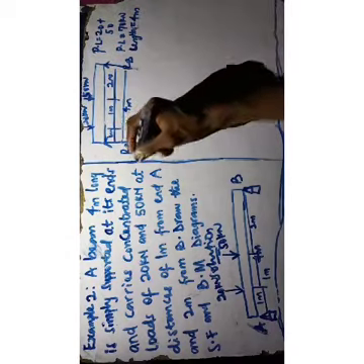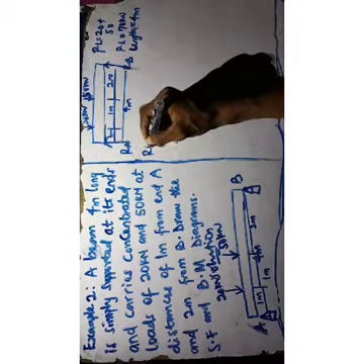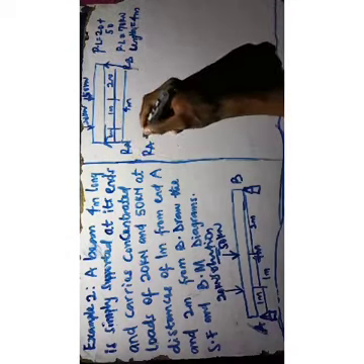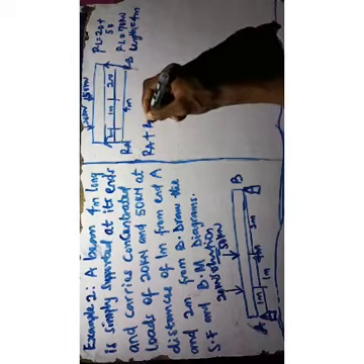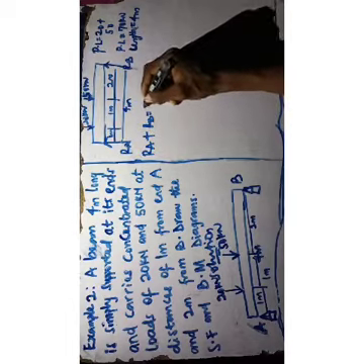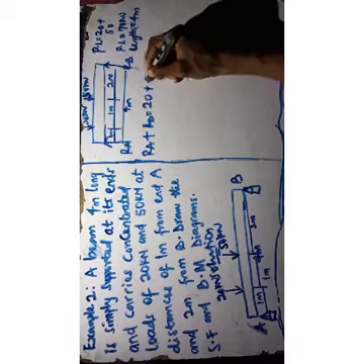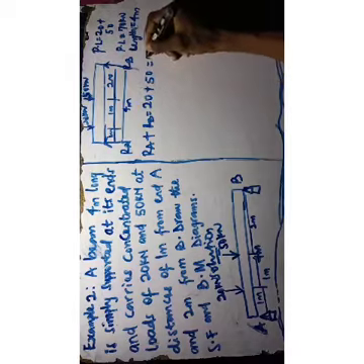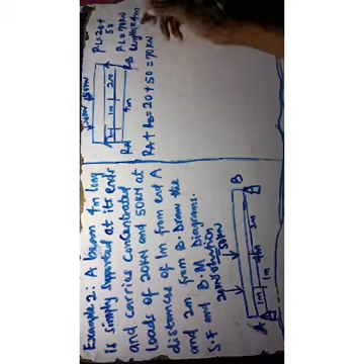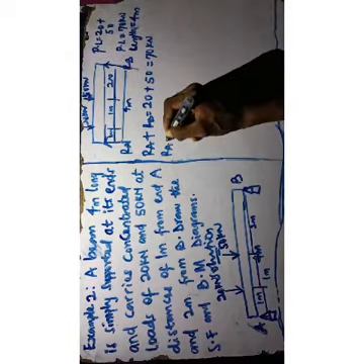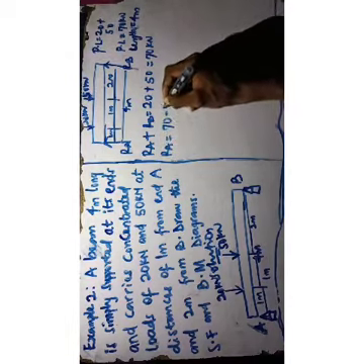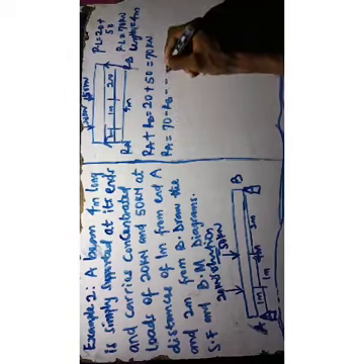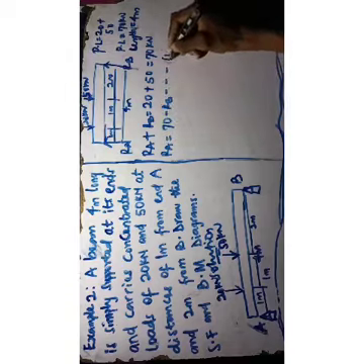Then your total length of the beam is what? 4 meter. So first thing is your reaction. So taking reactions from both ends, you have it as what? Clockwise equals Ra plus Rb, because 20 plus 50 equals 70, and therefore Ra will be equal to 70 minus Rb, equation 1.